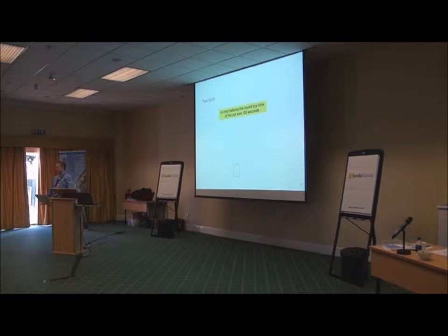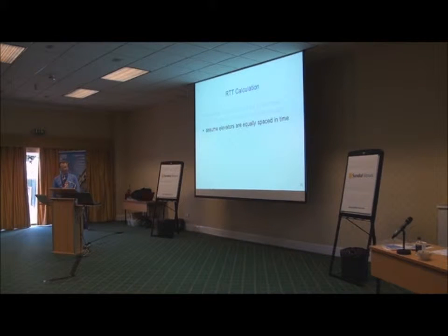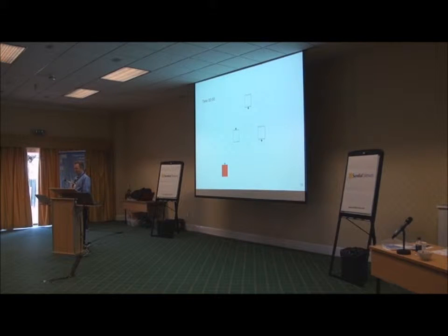And our whole traditional model is based on just that single round trip of a lift. And there are some really exciting formulae, which we can talk about if you're interested in them, to work out the probable number of stops and the highest reversal floors and stuff like that. If you're interested in those, you can look at the literature. So from the round trip time calculation, we estimate what will happen with more than one lift or elevator. And we assume that the elevators or lifts are equally spaced in time. So I should have changed this from elevator to lift because we're in the UK. I apologise, Gina.